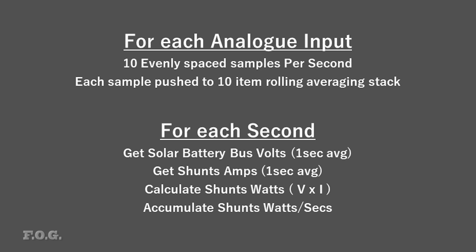And just FYI, I am actually purposely accumulating in watt seconds because the float mathematics in Arduino is totally broken. Actually, I originally did attempt to accumulate in the fractions of kilowatt hours, but the result I got was absolute garbage. So watt seconds accumulation is what I ended up going with. Actually, trying to accurately calculate accumulative power consumption is a whole story in itself. But I won't go into all of the coding details here, but let's just take a look at some of the general concepts.